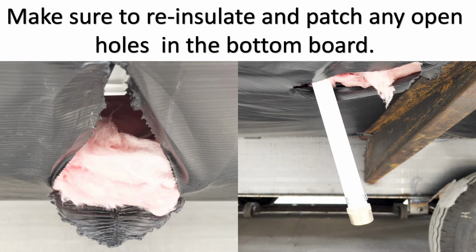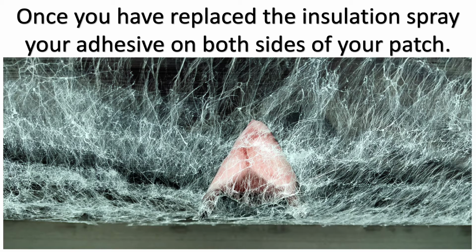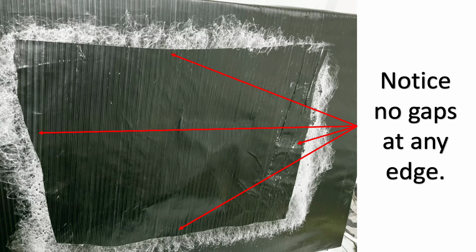Make sure to re-insulate and patch any open holes in the bottom board. Please use Q320 spray adhesive in a can or an equivalent for any bottom board repair. Once you have replaced the insulation, spray your adhesives on both sides of your patch. Always make sure to spray both the patch and the cut or the tear. Notice no gaps at any edge.